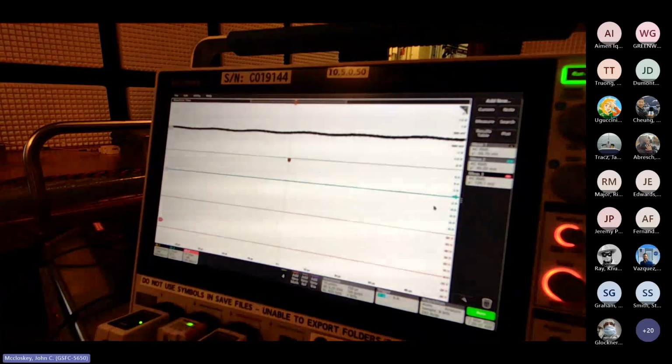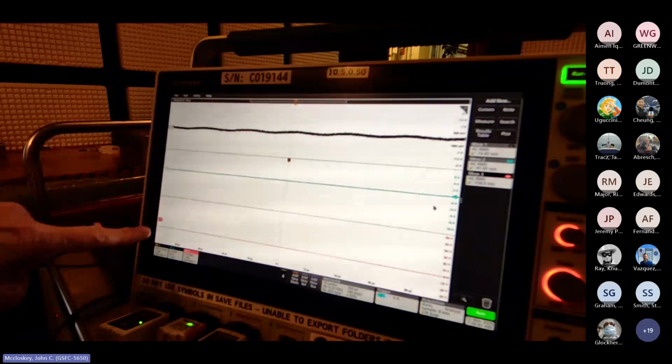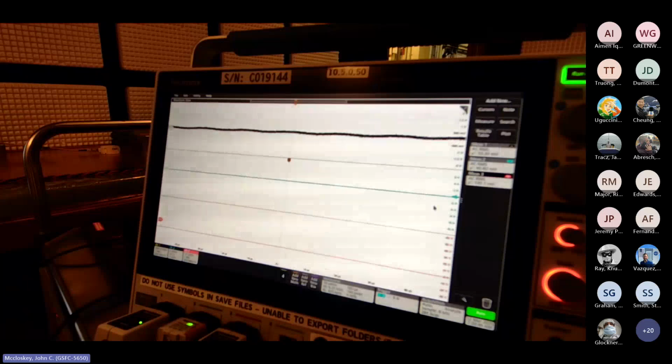One of the other points I'm going to make is you're going to be looking at AC ripple on top of a DC level, both for voltage and current, and the output level here, the plus 15 volt output. There's also a minus 15 volt output from the power converter as well, but they'll look pretty similar. And for sake of discussion, I'm only going to look at one.